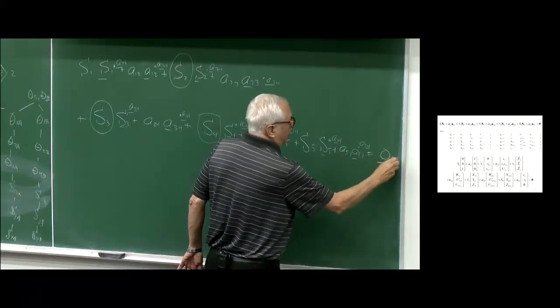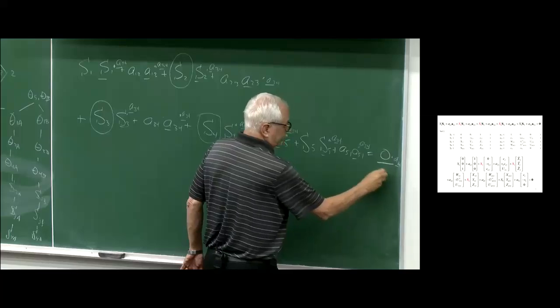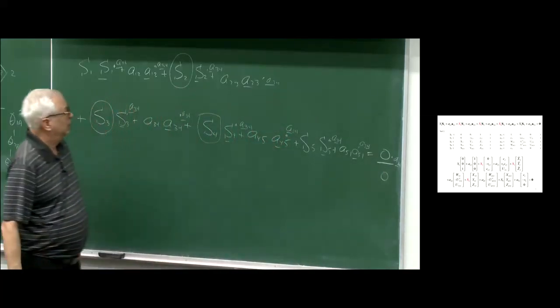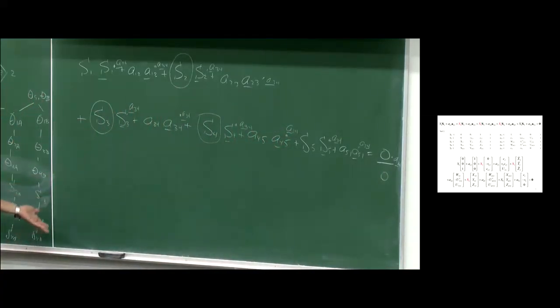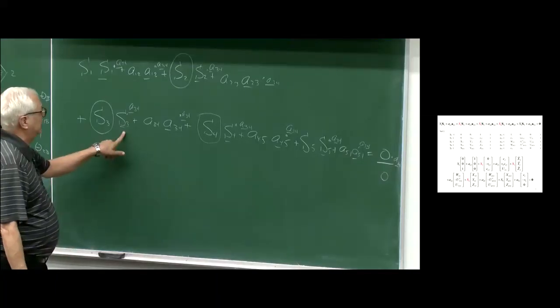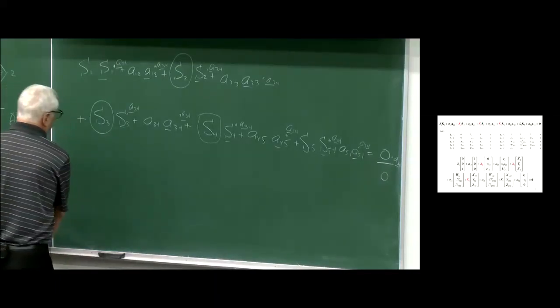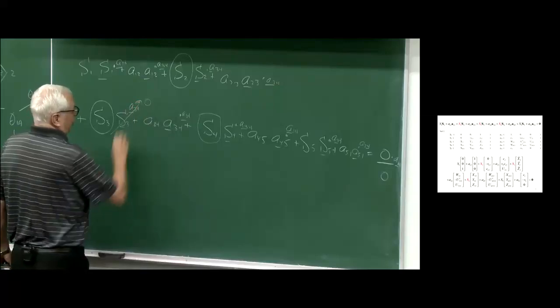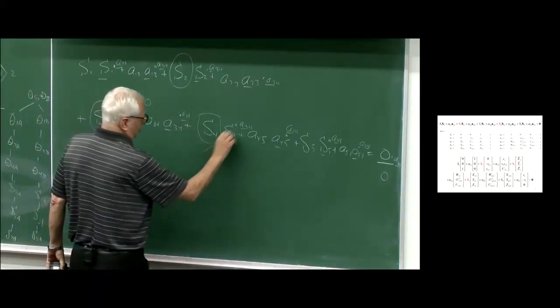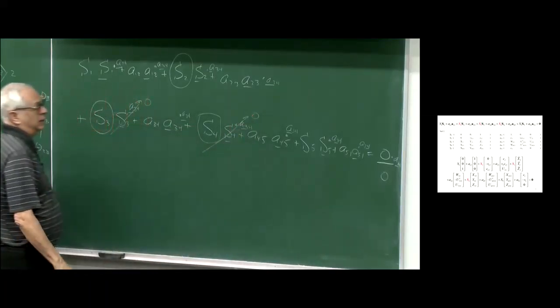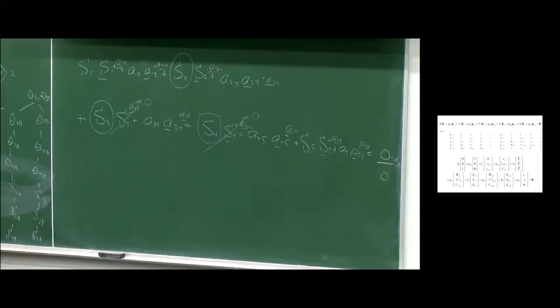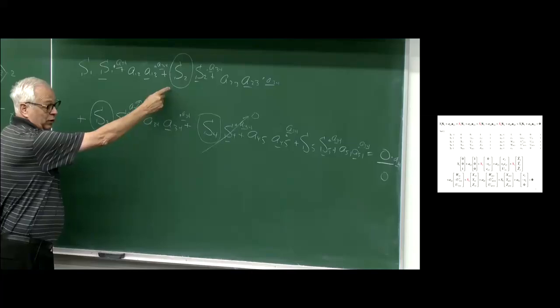Now over here, when I do dot the A34 vector, I'm going to get the zero scalar. If we do any of these dot products, you get a scalar value. So we're not going to have three equations, three unknowns anymore, but we're going to have one equation and three unknowns. But the reason I picked A34 is I knew it was perpendicular to S3, so I know that's going to go to 0. And I know A34 was perpendicular to S4. So I picked A34 on purpose because when I do the dot product, I'm going to get one equation and one unknown.